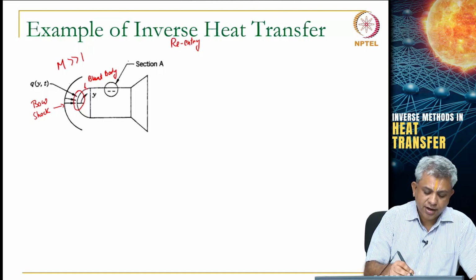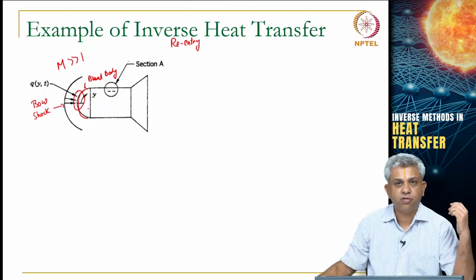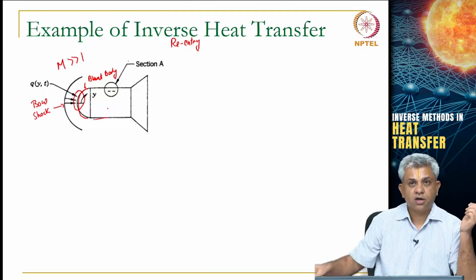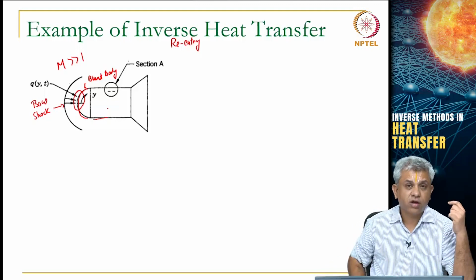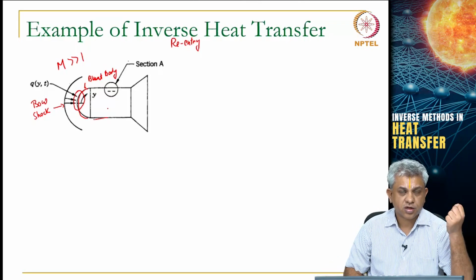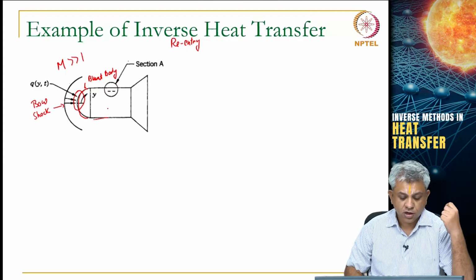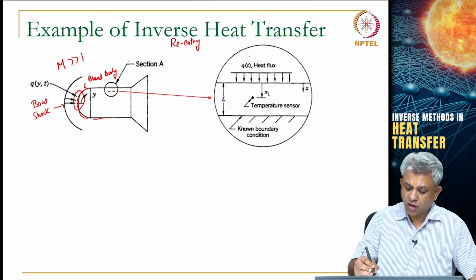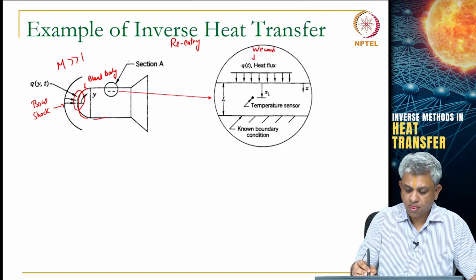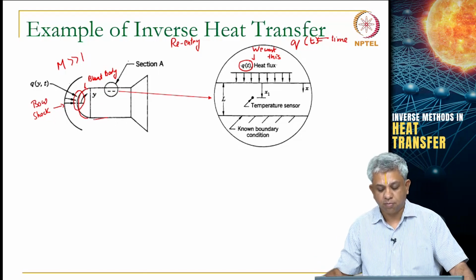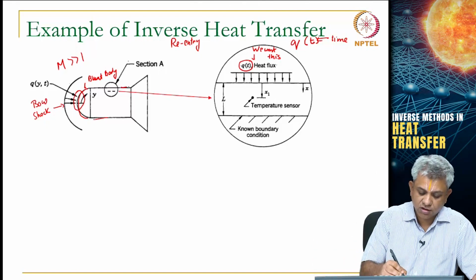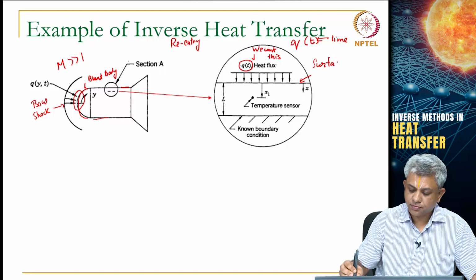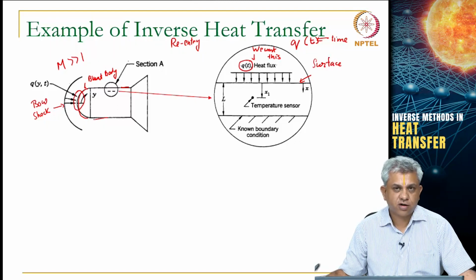Now, all this ablates. This material here is kept as protective material to protect whatever components exist here. So, it rapidly decays, and you want to find out whether it will be able to take the heat transfer load. You also want to make live measurements of this. Suppose I zoom in on this portion, what you will typically see is something of this sort. What you want to measure is this. It is not a single number, notice this is q of t, where t is time. You want heat transfer as a function of time at the surface. So, this is the surface here.